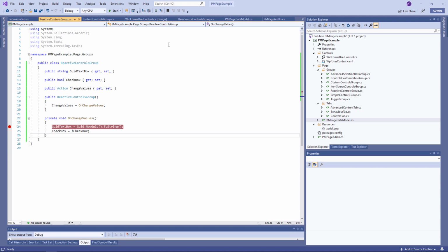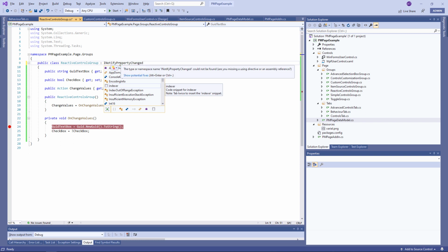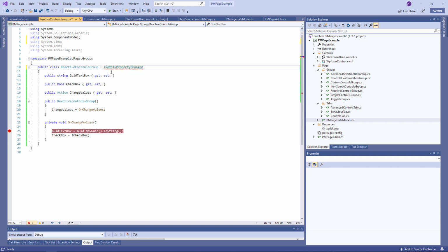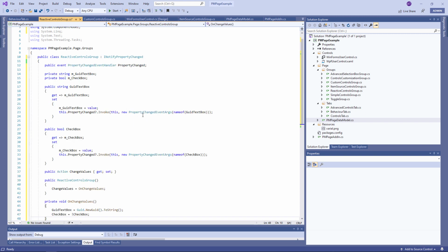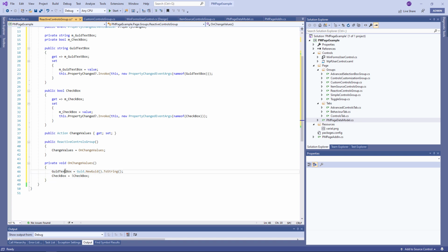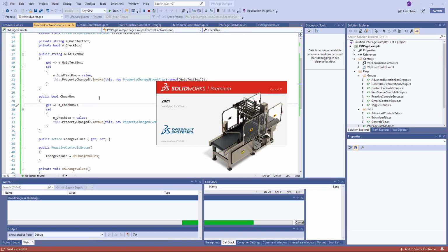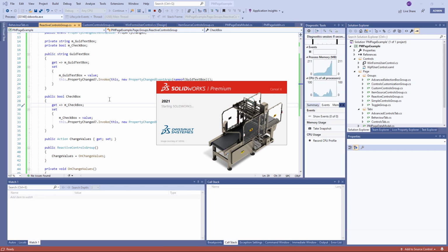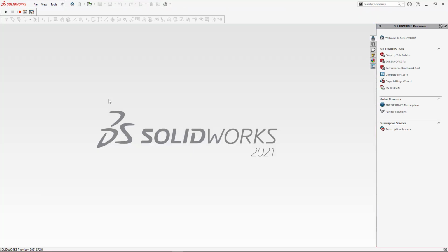If you have been developing applications with Windows Presentation Foundation, you'll know that it runs into a similar scenario. And this issue is fixed by implementing the NotifyPropertyChanged pattern. xcad.net supports the same mechanism, so in order to fix that problem, we need to implement the INotifyPropertyChanged interface in our data model and invoke the PropertyChanged event whenever our property value has been updated. The framework will process this event and update the controls correspondingly.